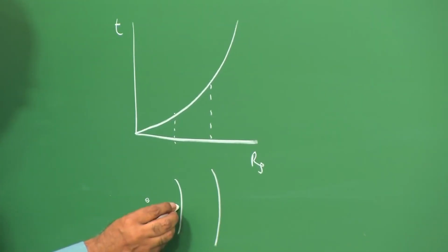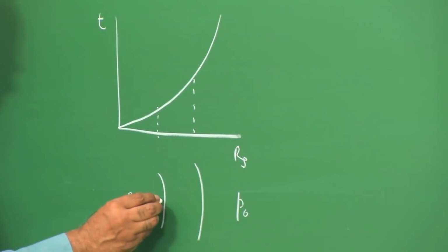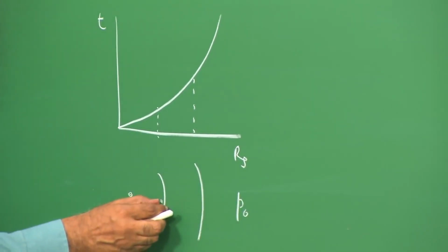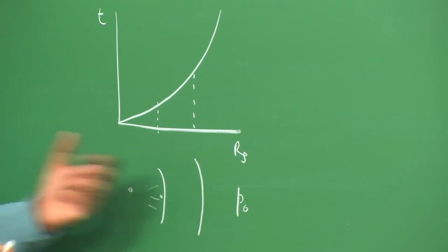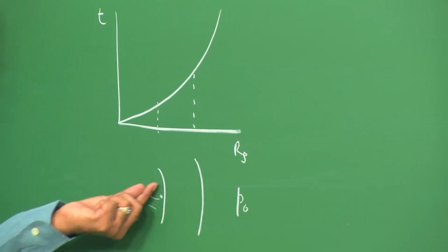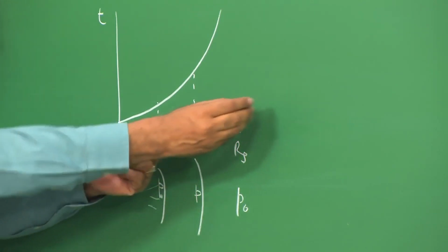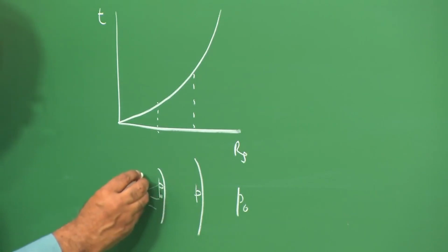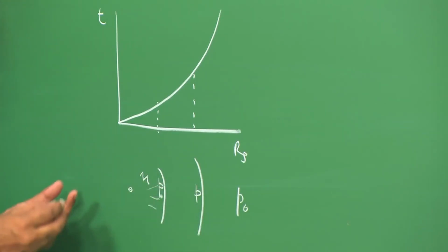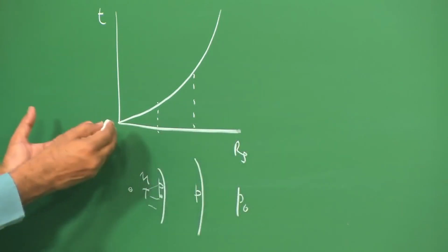We would like to know what is the pressure behind it when the ambient pressure is P0. We would like to know the jump in pressure, and also the wind effect, what are the velocities behind it which give the impulse. Therefore, to be able to calculate the pressure at the different points as the blast wave progresses, we wanted to know the value of pressure, the value of the velocity, and the temperature, etc., as the wave progresses.